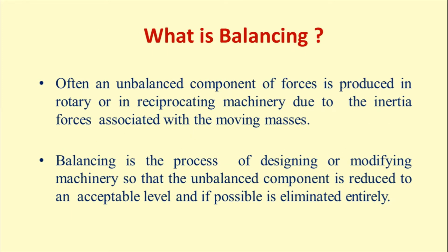The question comes: what is balancing? Often an unbalanced component of forces is produced in rotary or reciprocating machinery due to the inertia forces associated with the moving masses. This is very common in different types of engines, because the crankshaft is not of regular shape and size.